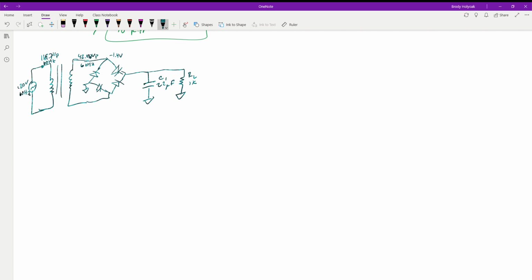So coming out of our rectifier, we have a 41.033 volts peak signal at 120 hertz. Because just like the other one, we took the inverses, the two 180 degrees out of phase, and we end up with the two peaks coming out of this. And you can actually measure that. You plug it in there, you'll see that.